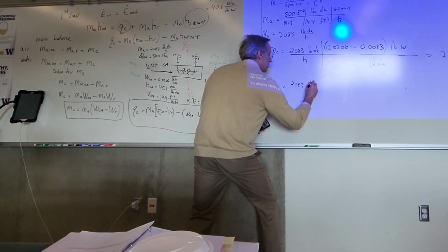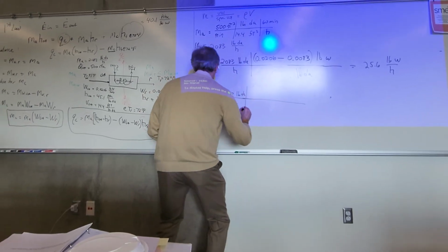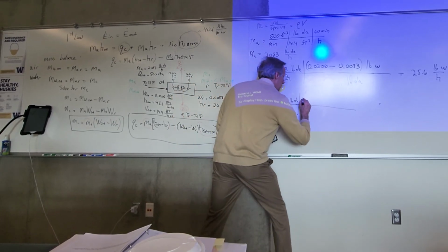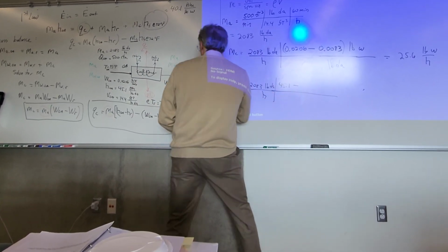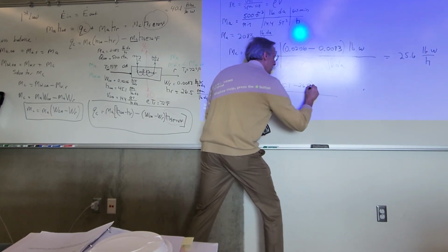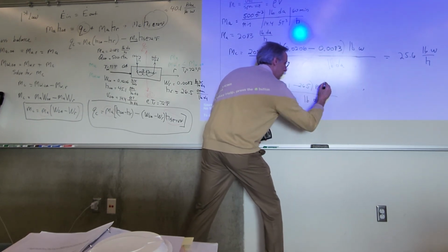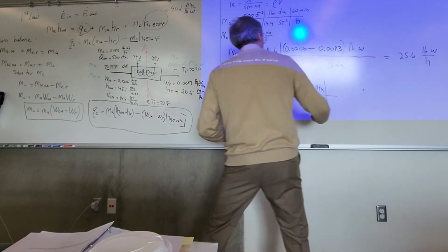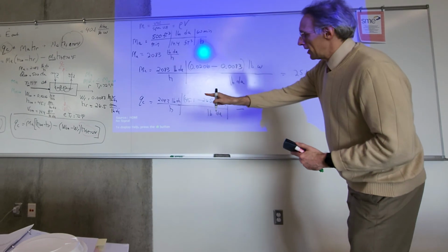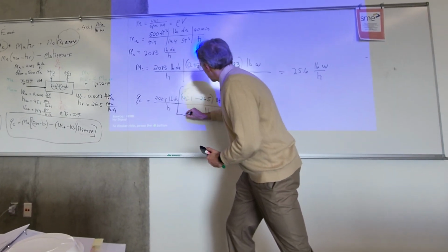And then QC is 2083 pounds of dry air per hour, and HOA is 45.1, HR 26.5, and the units there are BTU per pound of dry air. Okay, so now minus, that's going to be in brackets there.